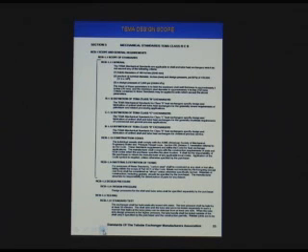In some cases where we have alloy exchangers, the alloy material may or may not have a corrosion allowance. If we have a clad vessel where we have carbon steel with an alloy clad, the alloy clad typically would have the 1/8 inch corrosion allowance applied to it. So once the clad material is identified, there is no additional corrosion allowance that's applied to it.